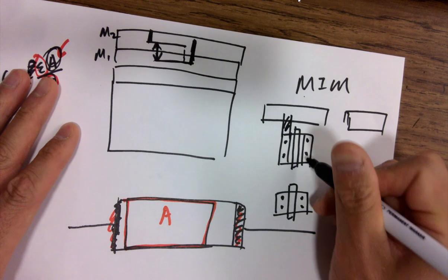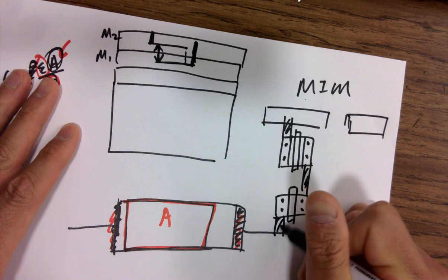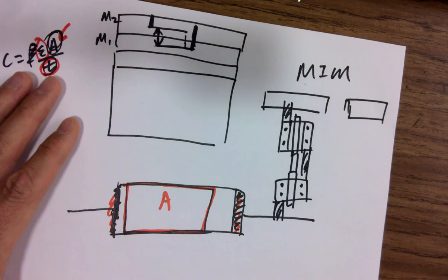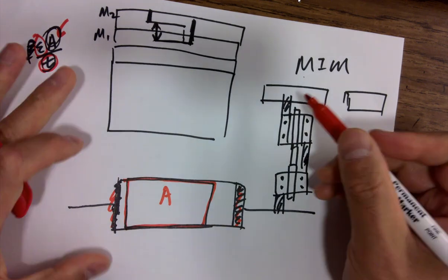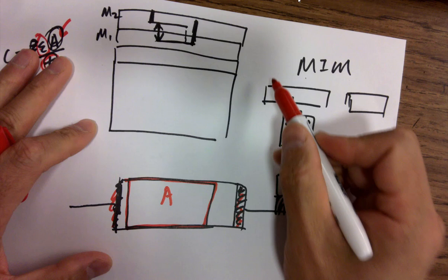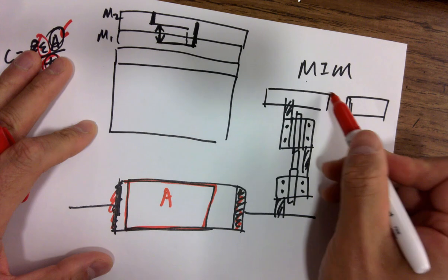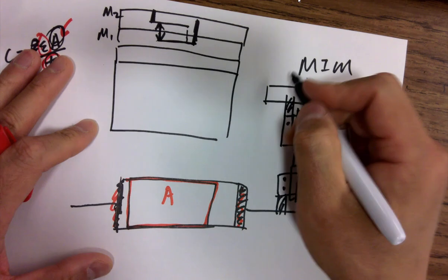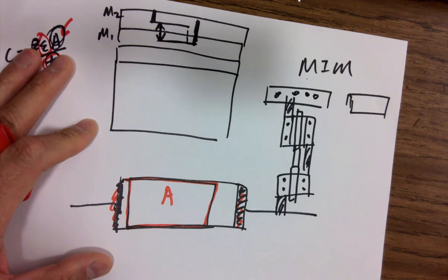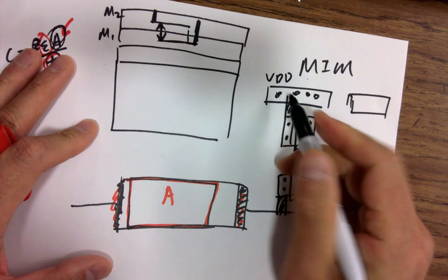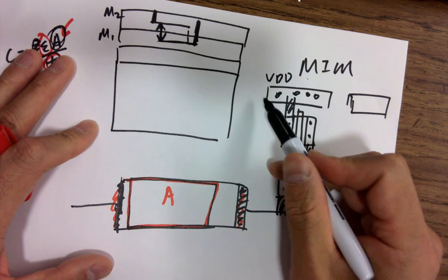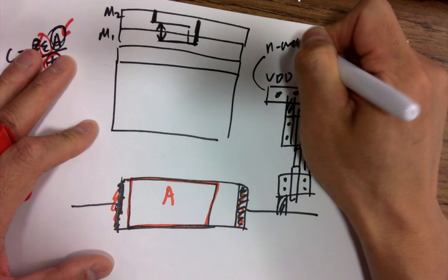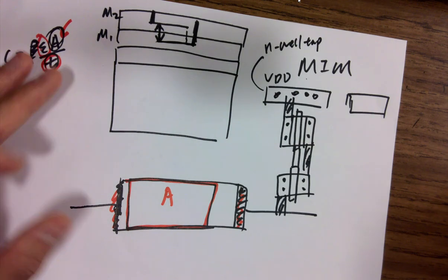Alright, do this. That's an inverter, right? What is this? It's a VDD. Yeah, VDD sometimes you don't want it to be VDD, just let you guys know. So for general cases it's VDD, but what are these components? What's the name of the part in the library? Well, it's a well tap, an N-well tap. And we just shorten N-well tap to VDD, okay?